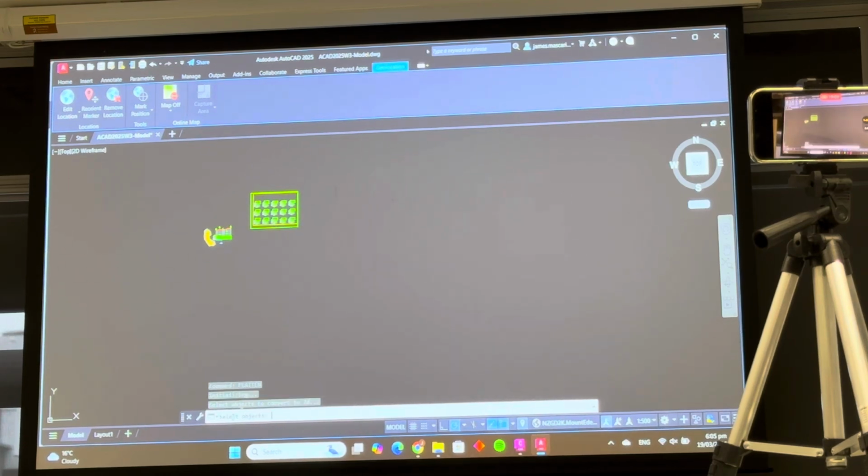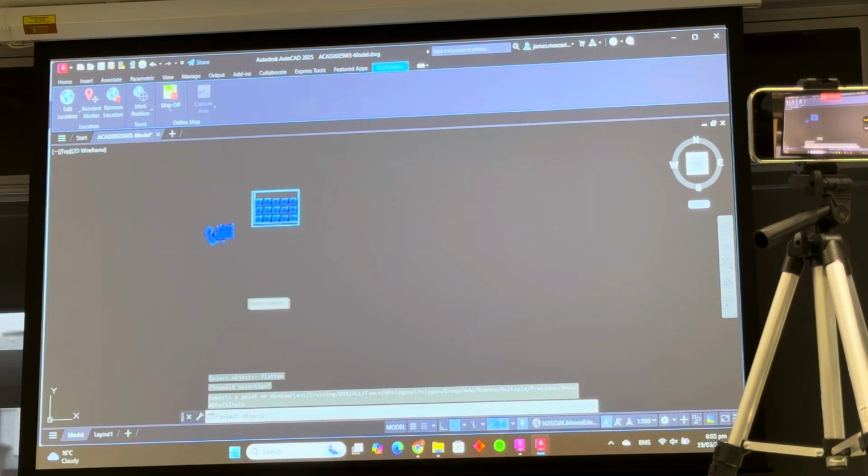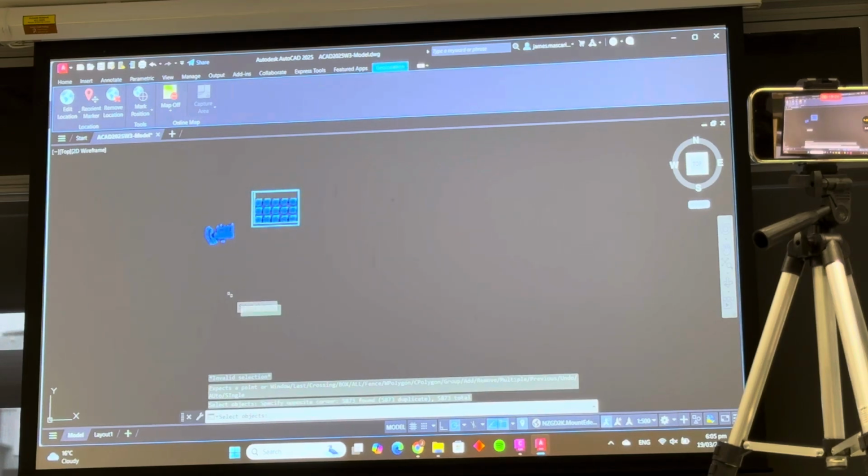Flatten. So, oh sorry, you're supposed to select all the objects. I might as well select everything, but to be honest, the cross sections and long sections and the profile don't need it. Let's try again. FLATTEN, enter. Select the objects, enter.